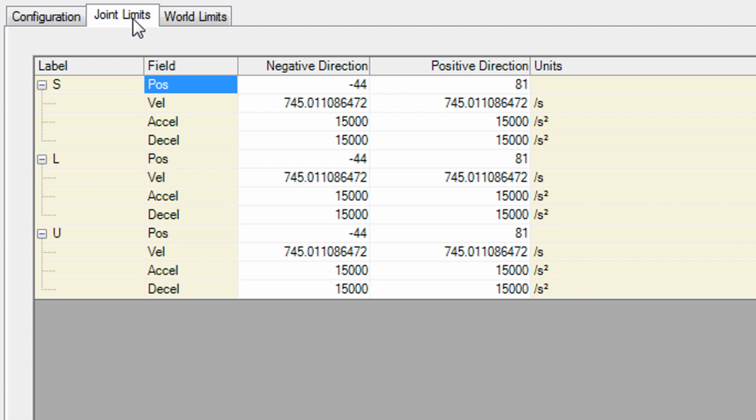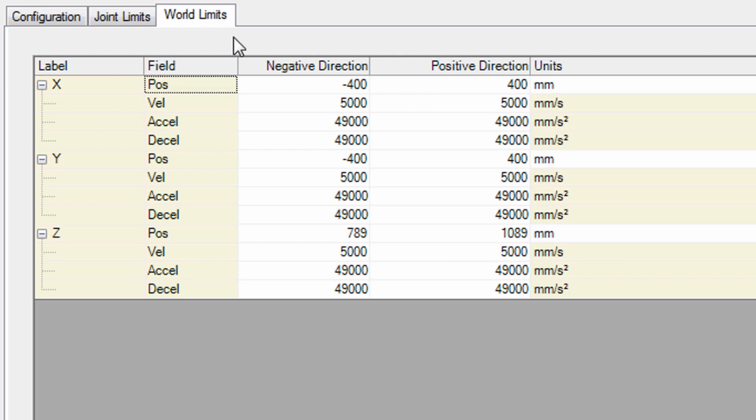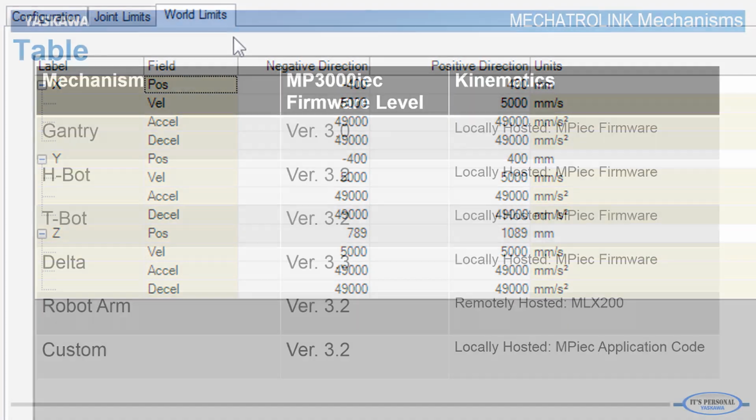Collision and breakage can be avoided by establishing software limits that define the range of motion for each axis. In the case of the Delta robot, each axis has limits regarding the leg angle, speed, and acceleration. But these limits are distinct and defined separately from the limits of the tool moving within the Cartesian workspace. And that can be set here.